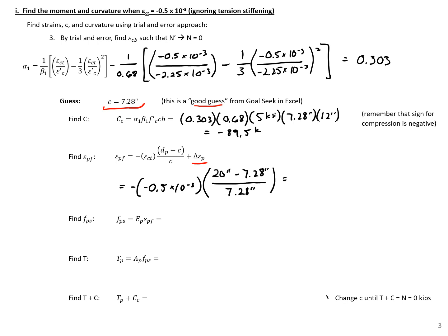And we'll get this value here to be, and then we add in our locked-in strain differential, so plus 6.0 times 10 to the negative third. And we'll get the strain in our pre-stressing to be 6.87 times 10 to the negative third.